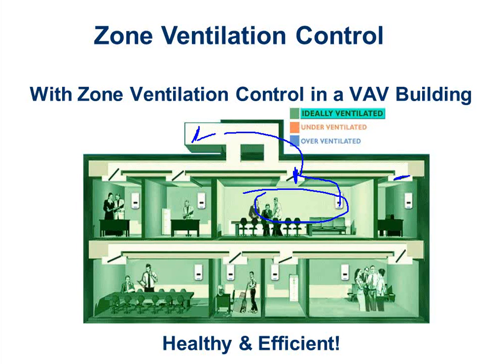So for example, if this particular conference room was required to have 300 CFM total for a normal job, when I put DCV on there, maybe I'm going to modulate it between, say, 100 and 300 CFM, 100 when no people are there, because I still need to take care of any off-gassing of equipment. And I can't tell for sure if nobody's there or not. At nighttime, you could let it go fully shut because it's technically unoccupied then.